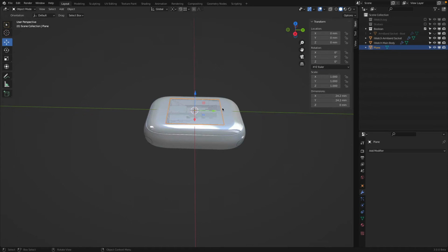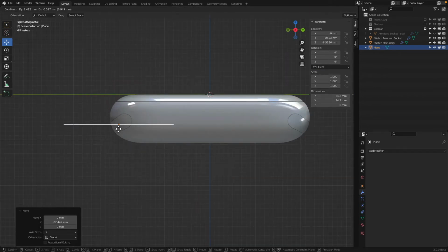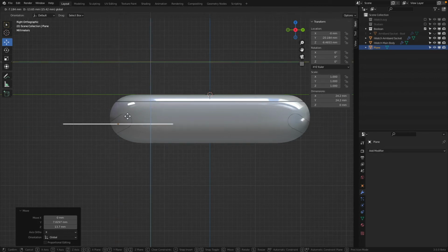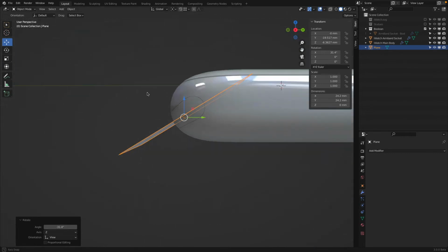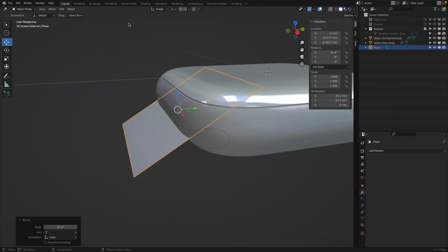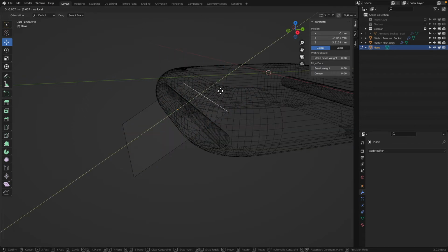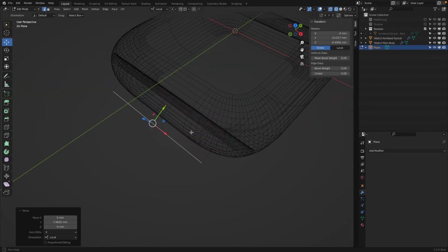Goodie. Tab, so we're back in object mode. Move over. By the way, you can actually, in the side view, go 2 directions. There. R and rotate in object mode. Very good. Now I can turn on local, go into edit mode via Tab, edge select, Z and wireframe, select this, move this back, and X and delete, select this, move this forward.